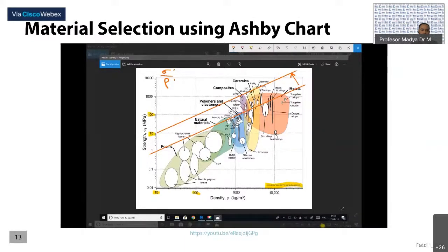What you notice now is that there's very few materials still in the running. We can see that carbon fibre reinforced polymer, here as an example, would perform very similar to diamond in terms of strength to weight ratio. But we can see various other materials, such as our steels are underperforming, and also our aluminium alloys here are underperforming.